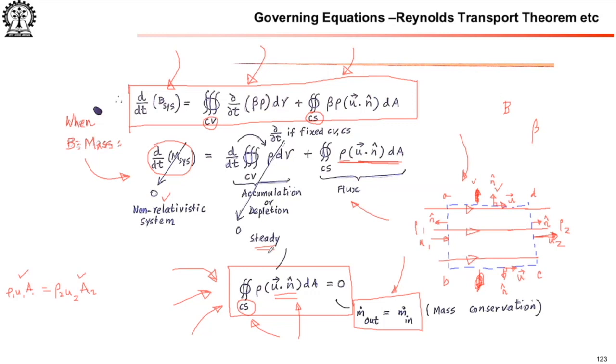Now again, I should emphasize that you need to find the direction of the unit normals at those regions, and the direction of the velocity vector at those regions. Here we chose the control volume in such a usable geometric shape, where on the top and the bottom walls, my unit normal and my velocity vector are directed in such a way that the dot products become zero.